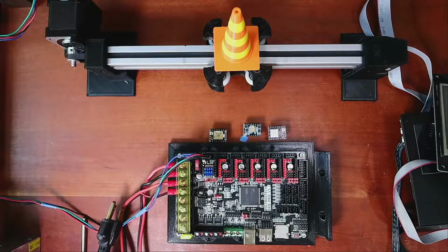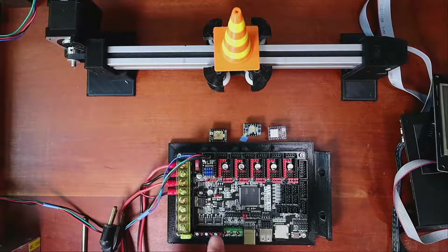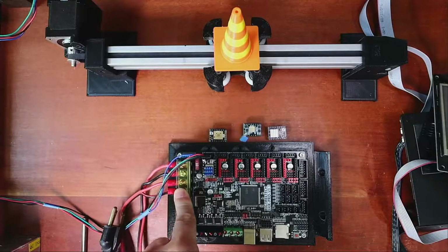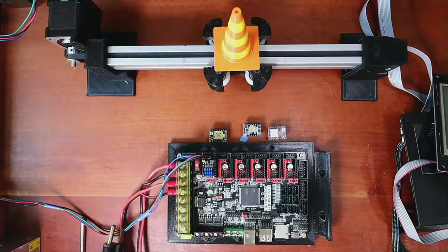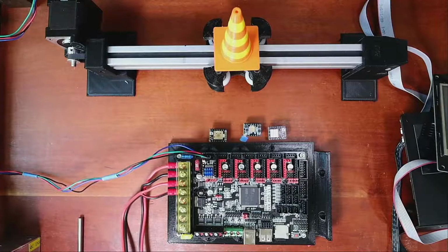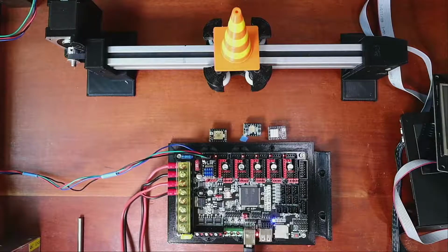Now there's a couple of ways to load it. The jumper for VCC or USB. Currently I'm in VCC, which would be direct power mode. We're not using that currently. We're going to use the actual power from the USB, so I'm going to move the jumper. You remember you have to move that back after you've loaded in order for your steppers to act properly. So I'm going to grab the USB cord, and you'll see a little flashing light probably in here, and that's the firmware loading. So that little ding is good.